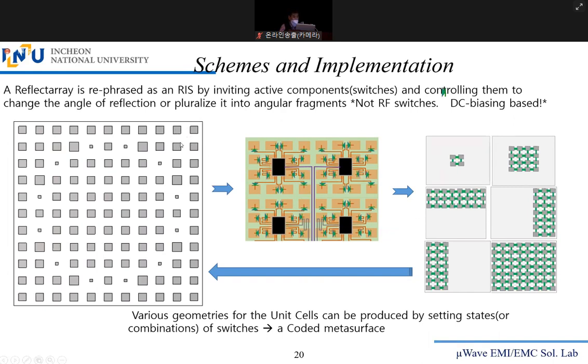So you take this, or you can determine the minimum unit or block, which is called the subarray in the antenna field. You should take the subarray 2x2 or 4x4, then take it. That means what happens to that subarray or new unit cell or group is going to be replicated to the rest of the whole structure. So the rest is history.